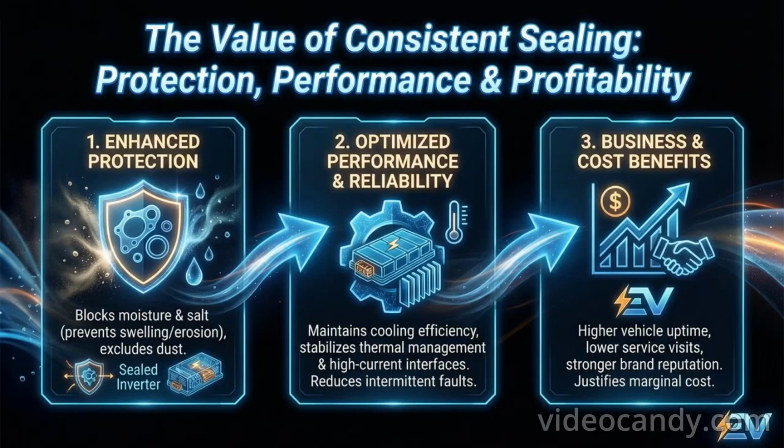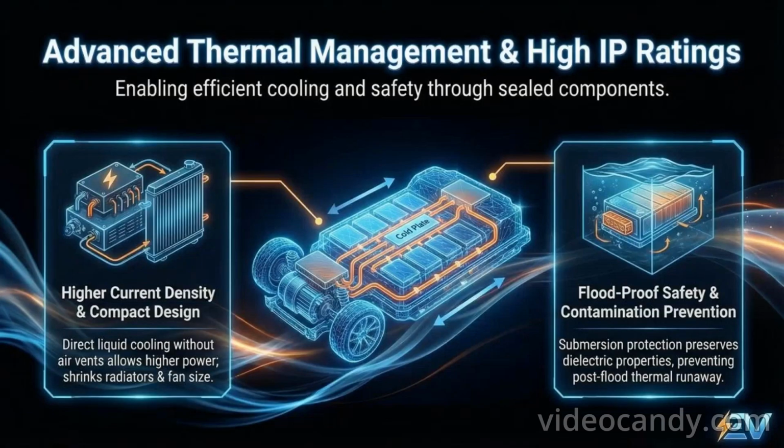Consistent sealing blocks moisture that swells conformal coatings and salt that erodes solder joints, extending inverter and battery life beyond 10-year warranties. Dust exclusion maintains cooling fin efficiency and connector spring force, stabilizing thermal management and high-current interfaces. The resulting drop in intermittent faults translates to higher vehicle uptime, lower service visits, and stronger brand reputation, justifying the marginal material cost of upgraded gaskets and O-rings.